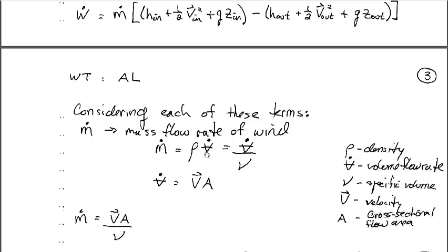And of course, as I've mentioned in class already, we don't usually talk about things on a per volume basis. Note that density is mass per volume. We always talk about things in thermodynamics on a per mass basis. So rather than write this as density, it's better to write it as what we call the specific volume, which is just the inverse of density.